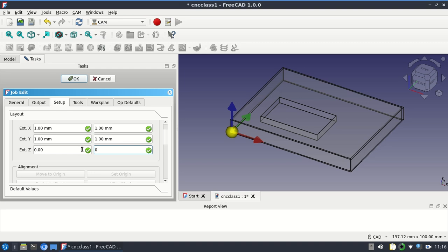Let's say I don't want this to be rough. So it would actually take a pass on top to smooth it first, right? Then you'd have stock on top. But for us, we're not gonna have stock on top. It's already gonna be our piece, right? So that's why we do 0 on top and 0 on the bottom.